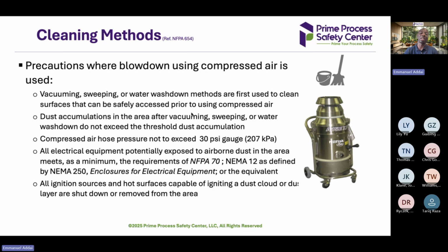How do we actually clean? If the dust cannot stay inside the equipment, it will automatically come out and accumulate on something. The most common and preferred method is using vacuuming, with ATEX-rated or Class 2 rated vacuum cleaners. I don't work for NFPA, but I see that some of their products are really good. After that, you can sweep, or use a water wash down. With water wash down you need to be careful. If you are handling combustible metals such as aluminum and other reactive metals, you don't want to use water.